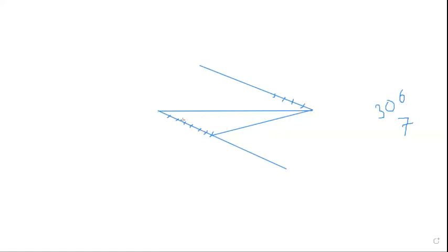So this is another way. Both angles will be this angle and this angle, both angles will have the same dimension and you divide the two lines with the same division. Okay, here you divide the same dimension, you divide by using the compass. Then join this like this. So in this way, you can also divide the line. For this, you do not require the parallel line. It must always be parallel, but if you divide in this way, your drawing will not be a better way.